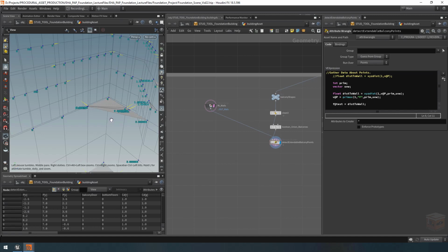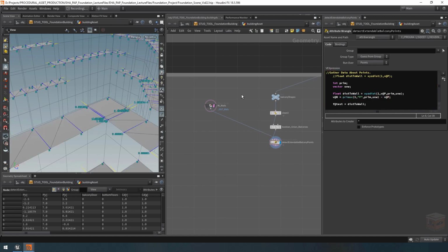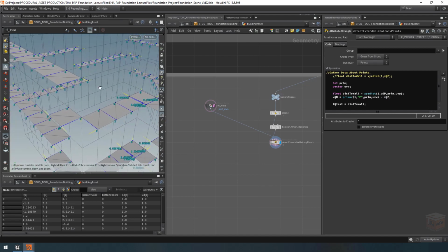As a result, we've basically now snapped all of our points to the wall. Now, maybe we don't want to do that. So instead, let's actually retrieve the normal, or the direction that these points would have snapped in. And we can do that instead by writing to the normal attribute. Then we can take this coordinate that we retrieved and subtract our current point position from that. If we do that, then all of our points are going to aim at the closest location using a normal vector where they would have hit the other surface.